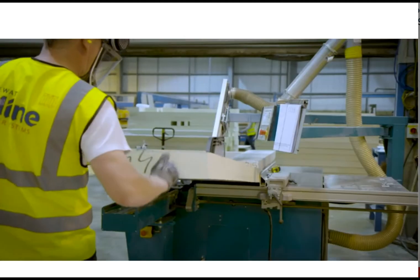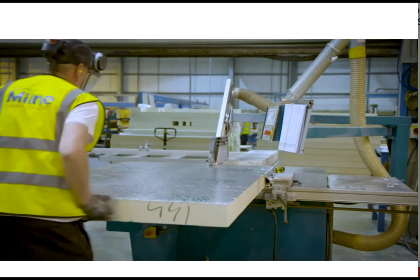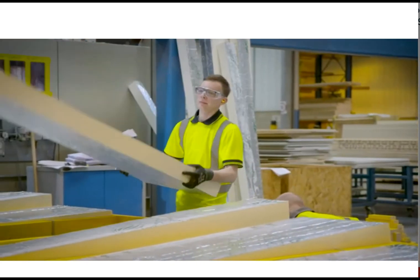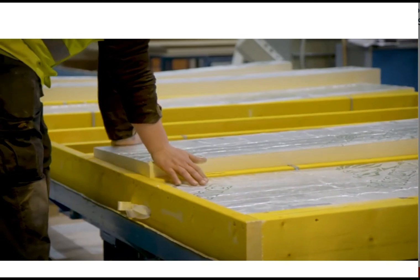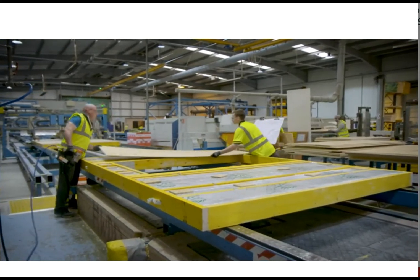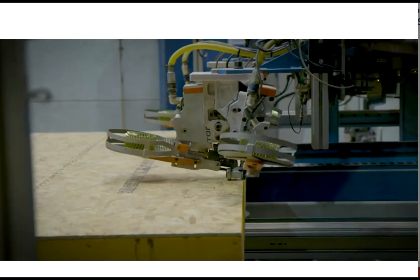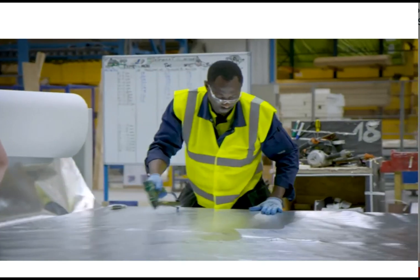To achieve current building regulation standards, 100mm of foil-backed polyurethane insulation is carefully cut and then placed between the studs of the timber panel, making sure all spaces are fully filled. A 9mm OSB sheathing board is then applied to the frame to provide rigidity to the panel. This is nailed into place and provides a backing to the reflective breather paper, which is added next.